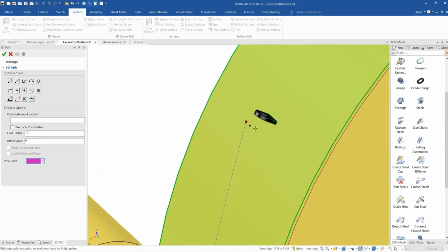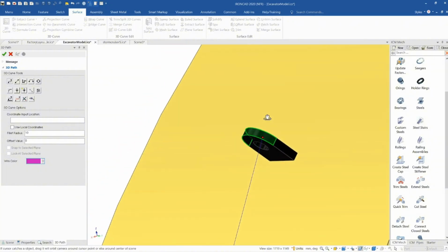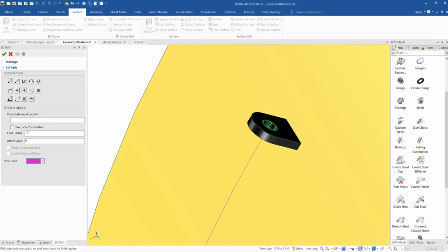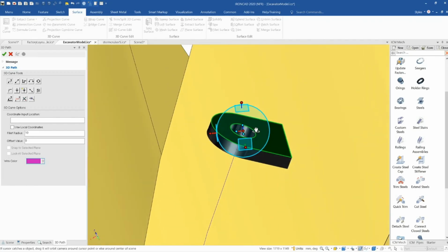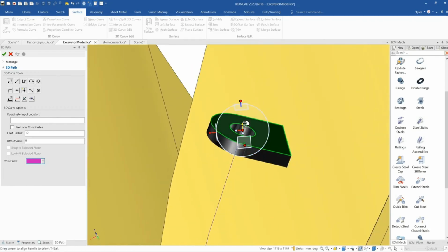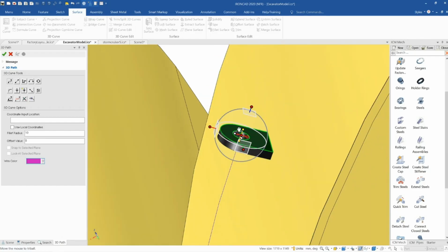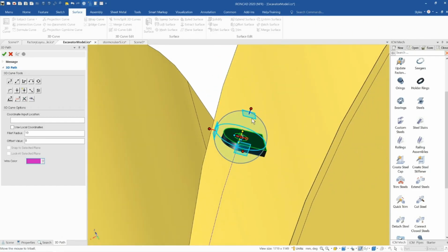And then we're going to go up and do the same up here. So I'm going to zoom in, and we could do it on both sides of this, for example, out the front of this and out the back, but I'm just going to do it out the back because it'll make things faster. So we're going to snap to these 2 points again. But now I'm going to activate the tri-ball and move to this center point. And now I actually want to align the tri-ball, so I'm going to hit the space bar and just align to that face. It's the same as right-clicking and selecting perpendicular to face and then clicking on that face. I just did it by dragging it, which is a little bit faster.